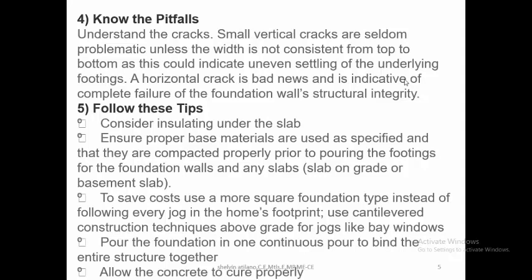Then the last one, follow this step. Consider insulating under the slab. Meaning, we are talking about slab on fill. Meaning, you need to insulate. Okay, if we are considering, let's say, mat foundation, because it's pure slab, you need to put lean concrete. Then ensure proper base material are used as specified, that they are compacted properly prior to pouring of the footing. This is also important. Okay?